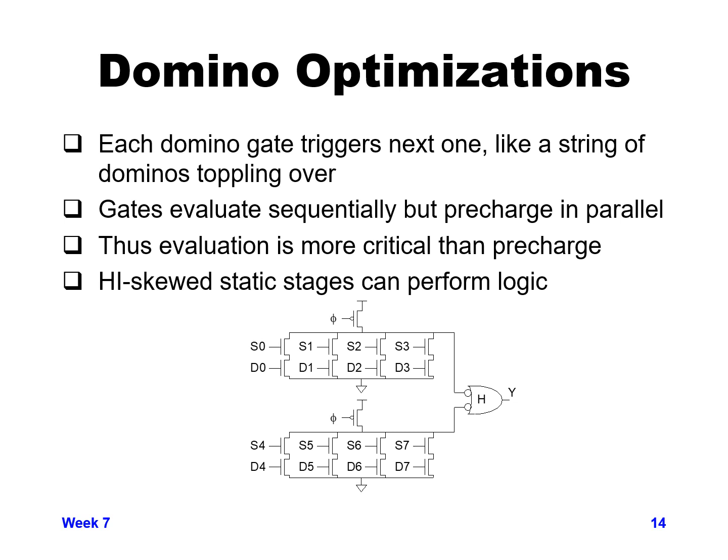So thus you have an entire phase to do your precharge in, but it's all happening at the same time, so the precharge can be relatively slow, but for the evaluation, you need to get all of your evaluation done in sequence, from stage to stage to stage, all in one phase of evaluation. So the speed of the evaluation is more critical than the speed of the precharge.